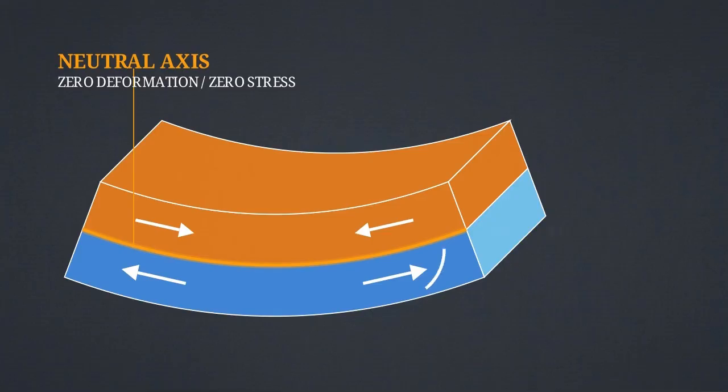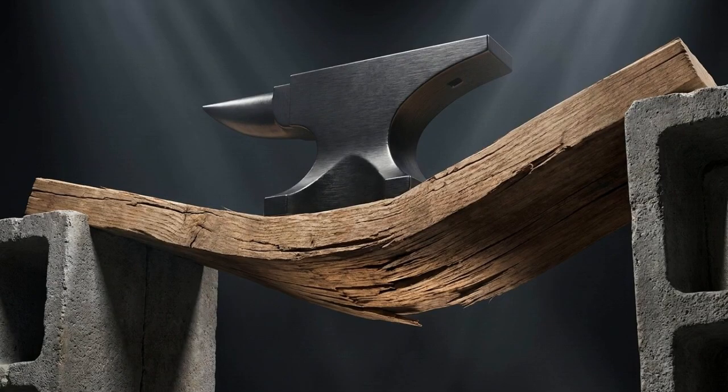This simultaneous push at the top and pull at the bottom creates a force couple. These two opposing actions link together around the neutral axis to form the total bending moment. This state, compression on top, tension on the bottom, is called sagging. It creates a positive bending moment, found at the center of a loaded span.